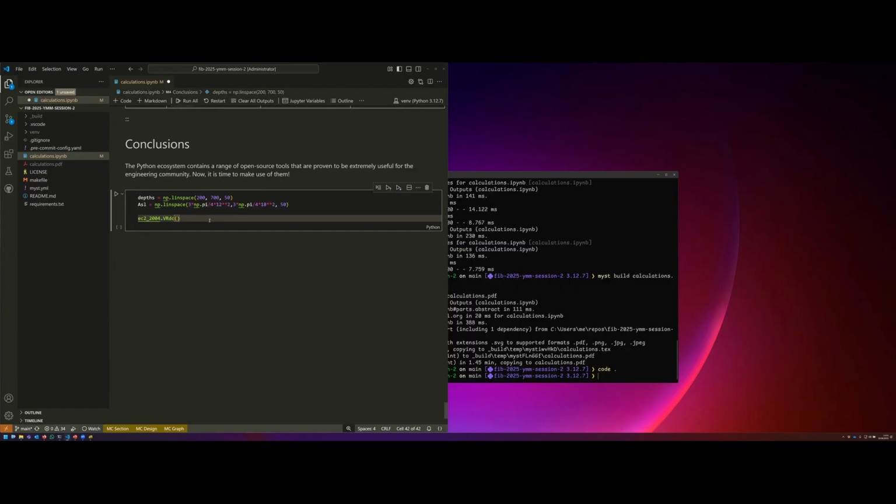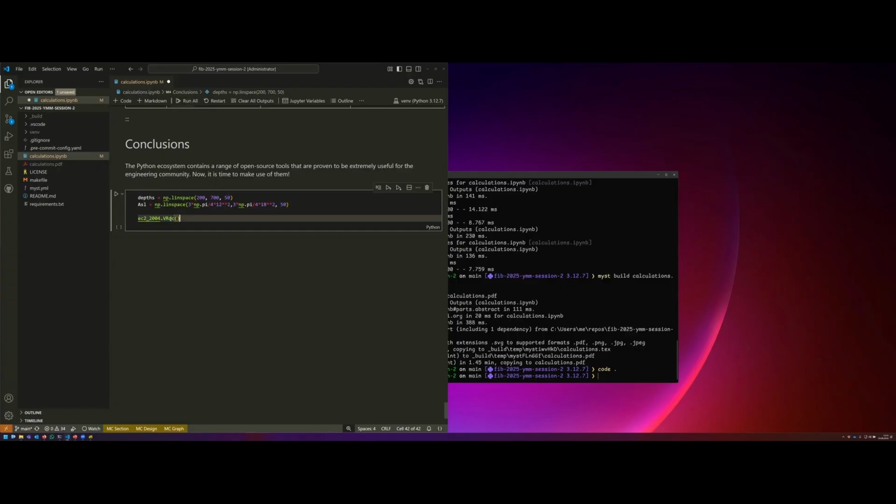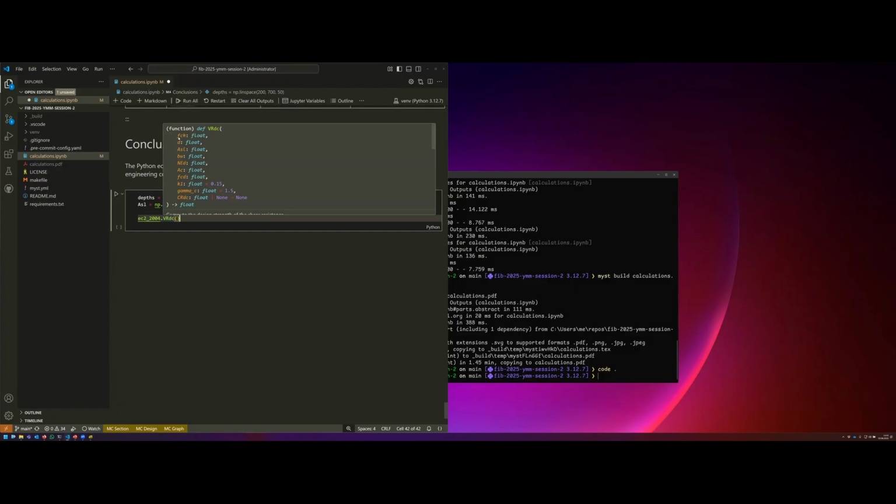That would require entering into the code and changing something, because I saw on screen that the gamma C can be defined, but the fck-fcm relation, I guess that goes deeper, or I would have to take care and adjust it so that I enter what I measured minus 8 megapascals so that the code operates. Yeah, well, I guess that depends on how you interpret this equation.